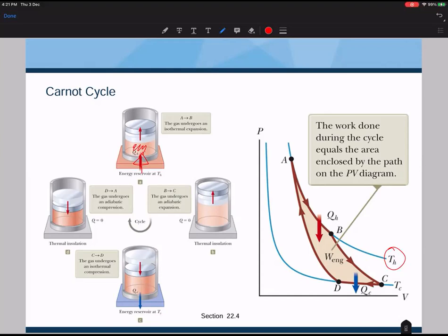Of course, the idea of a reversible process means that you try to keep the temperature difference between the gas and the reservoir to be as small as possible. When the temperature difference is small, heat transfer takes place over a very, very, very long time. So this would actually be a big problem, as we would mention a little bit later. But in any case, let us assume that it could still take place. Reversible process for constant temperature heat transfer into the engine.